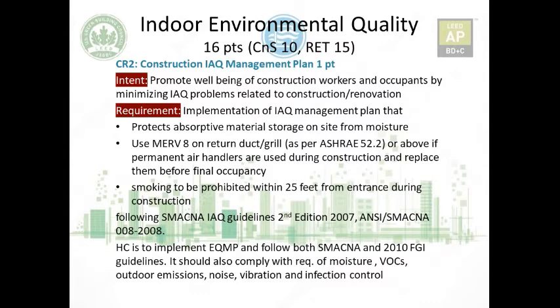Now, for healthcare, it should implement an environmental quality management plan instead of indoor air quality, and you know that in healthcare the requirements are more stringent, so it follows SMACNA and 2010 FGI guidelines. So it should also comply with the requirement of moisture we have seen, but additionally VOCs, volatile organic compounds, outdoor emission, noise, vibration.